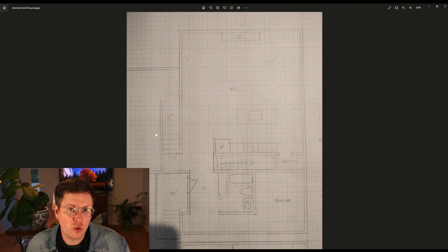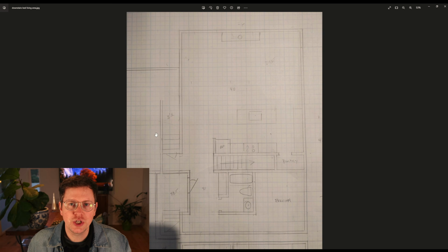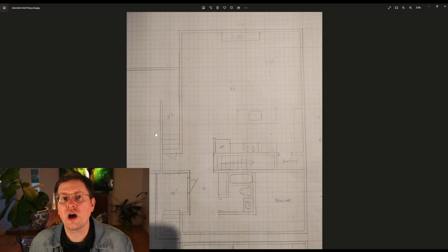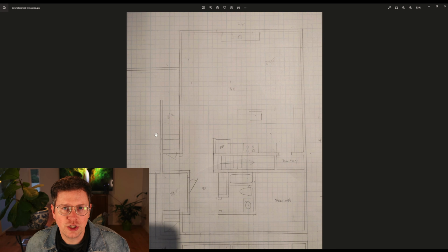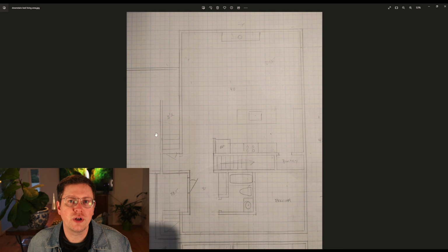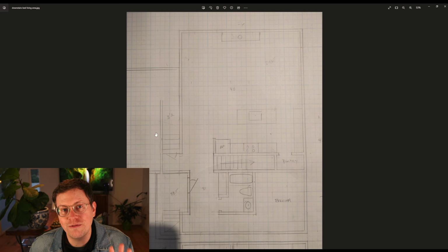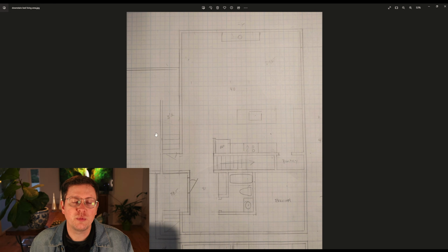There was nothing wrong with the layout in this design. But going back to what I was saying about trying to be economical about the packaging of the square footage, we found out that this layout with the garage to the side of the house was going to be more costly to build versus having all 3 bedrooms on the second floor with one of those bedrooms over the garage. So moving all 3 bedrooms upstairs and shifting the garage over decreased the overall footprint of the foundation and simplified the roof design, so we actually ended up saving about 50 grand in the quote for construction, and we still got the square footage, the bedrooms, and the garage that we needed.